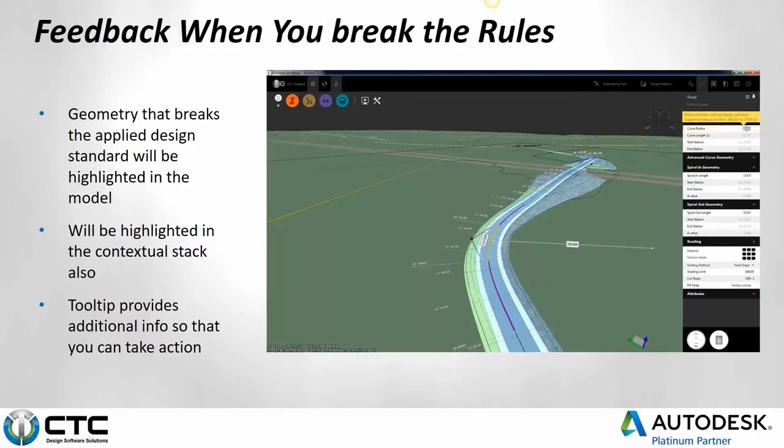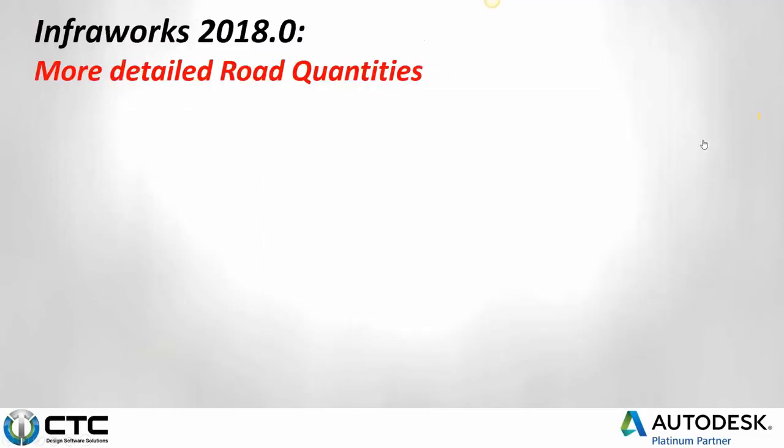Supported values are from 384 to 1708, and this curve radius was like 250 foot. So if your radius is too small, it's going to show up yellow. If your radius is the proper size or meets standards, it'll be green. If we want to see what's going on, we click on the alignment of the road, and then you'll be able to get the curve radius and curve length in there also.